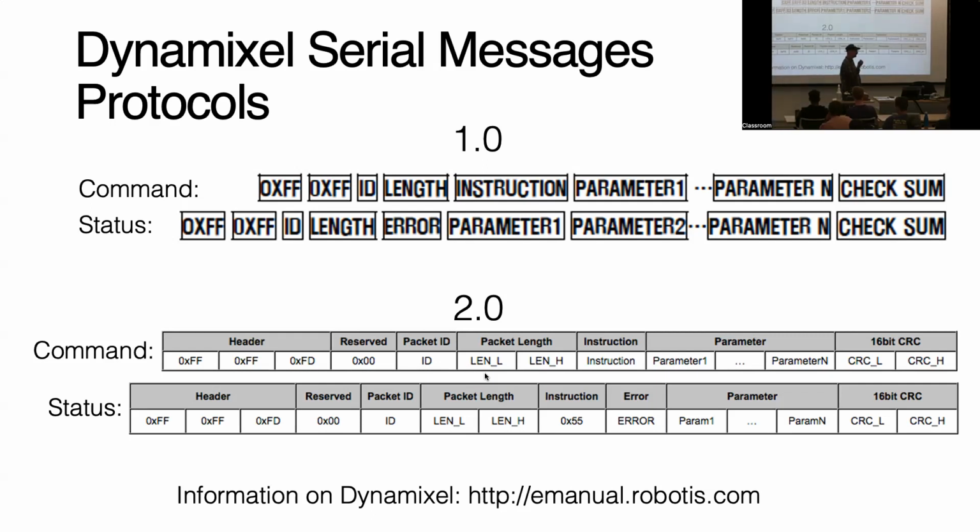Right, so you're sending these large packets back and forth between the motors, and you can do things like tell it what position to go to. You can do things like set the maximum speed, set the maximum torque. You can read back what position you're at. You can read back what speed you're moving. You can send a command to set the proportional gain or the integral gain or the derivative gain for your controller. There's all sorts of registers in these motors and commands you can send, all right?